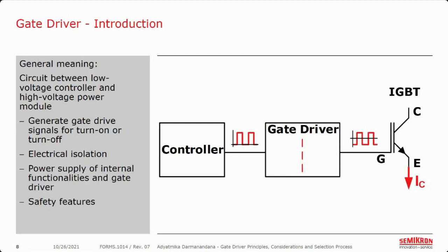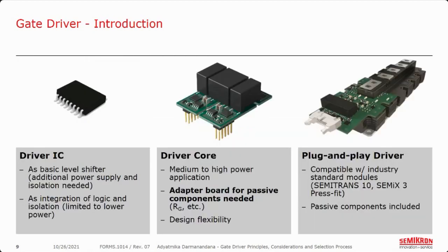Usually, a gate driver also provides isolation to safely separate the high voltage and low voltage parts. A fully functioning gate driver should also have the necessary power supplies to define the voltage levels that are required by the gate, and it can also have some other features for system protection. Depending on the application, a gate driver can be integrated with other functions on a single PCB, but in this presentation, we intend to assist you in the selection and implementation of an off-the-shelf driver.